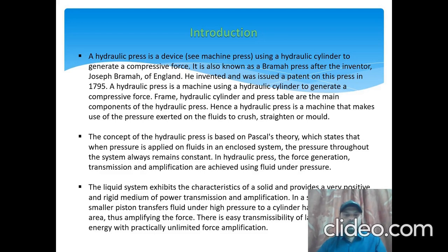The liquid system exhibits the characteristics of a solid and provides a very positive and rigid medium of power transmission and amplification. In simple application, a smaller piston transfers fluid under high pressure to a cylinder having a larger area, thus amplifying the force. There is easy transmissibility of a large amount of energy with practically unlimited force of amplification.